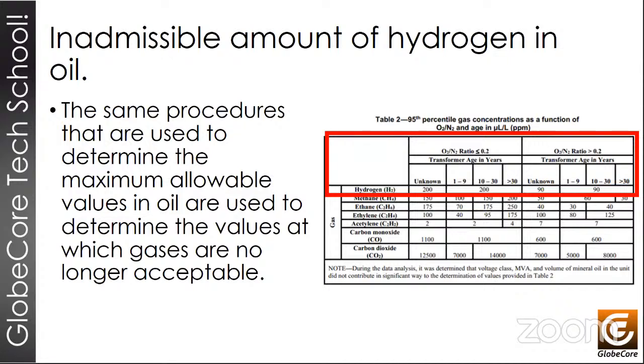It's important to clarify that when we have a problem associated with the formation of gases, we first tackle and address the element that generates the indicated gas, and only then we proceed to perform a degassing process. Because if we don't take corrective measures and just do the degassing, then very soon the oil will just have the same gas again.